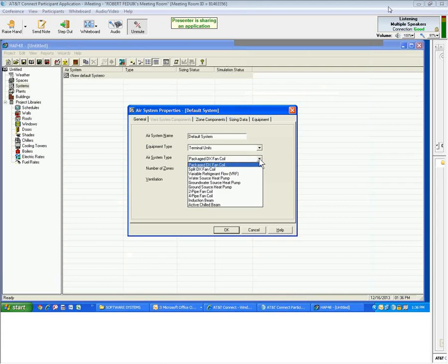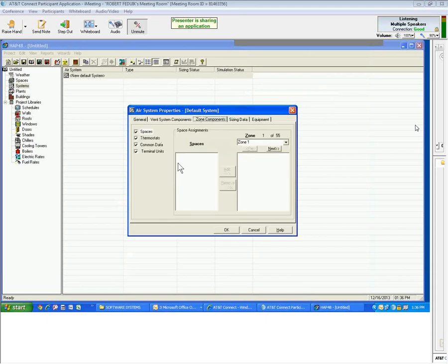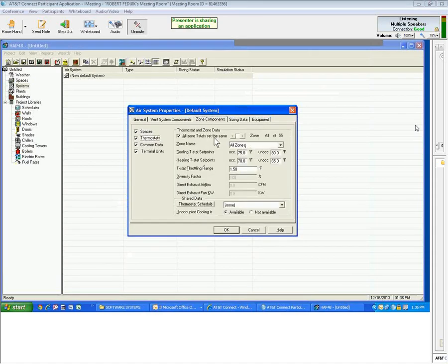So let's say you're doing a geothermal job and you're thinking of running a load and doing an op cost, and there are 55 units in the job. You don't want to put in 55 single zone constant volume water cooled units. You just say it's a terminal system, and you say that it's geothermal, and you put 55 in here now. You probably have a makeup air unit, and it goes through 55 spaces to become zones,